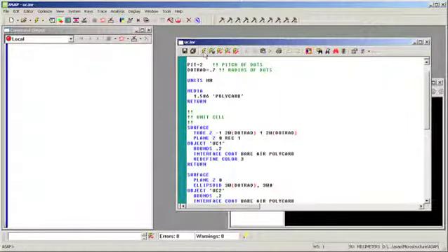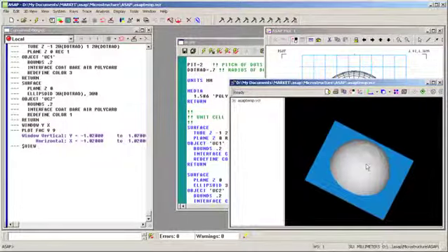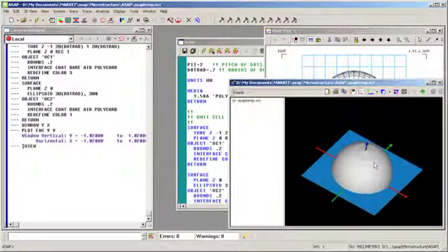When we execute this file, here is our unit cell. We see the ellipsoidal bump, and we see the plane boundary surrounding the bump. And if we bring the axes up, hitting the A key in the 3D viewer, we find that the z-axis, shown in blue, is indeed normal to the rectangular boundary.